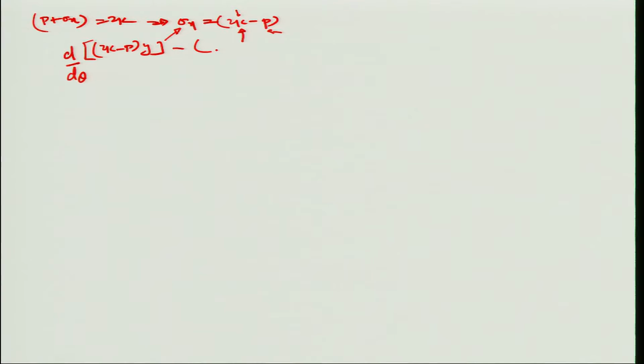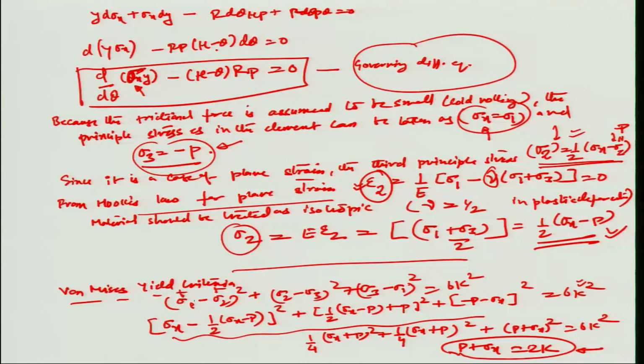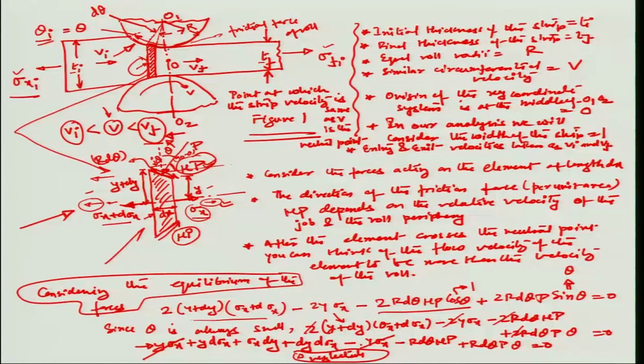Please understand one more issue: the direction of the friction force should change before and after the neutral point. In one case, the whole frictional term in this equation is an enabler, and in the other case, after the neutral point has been crossed, it should be a disabler. So we should consider the plus sign here. You remember the way we tried in previous slides to enable or disable this frictional force.